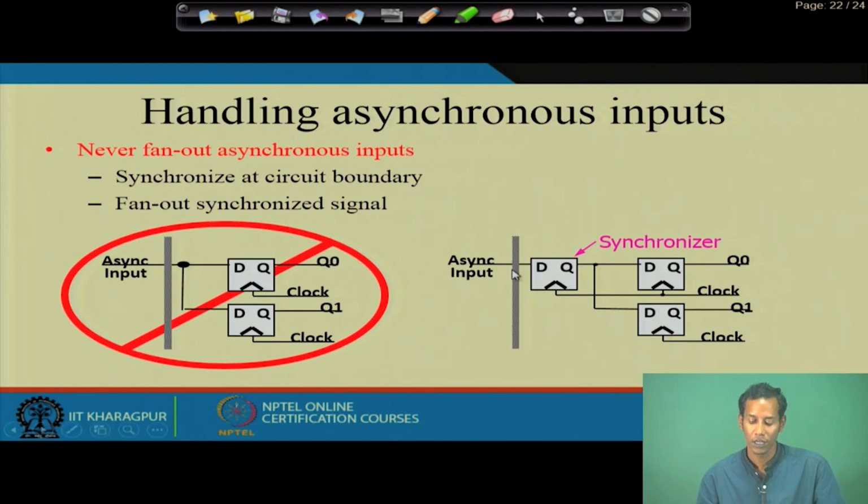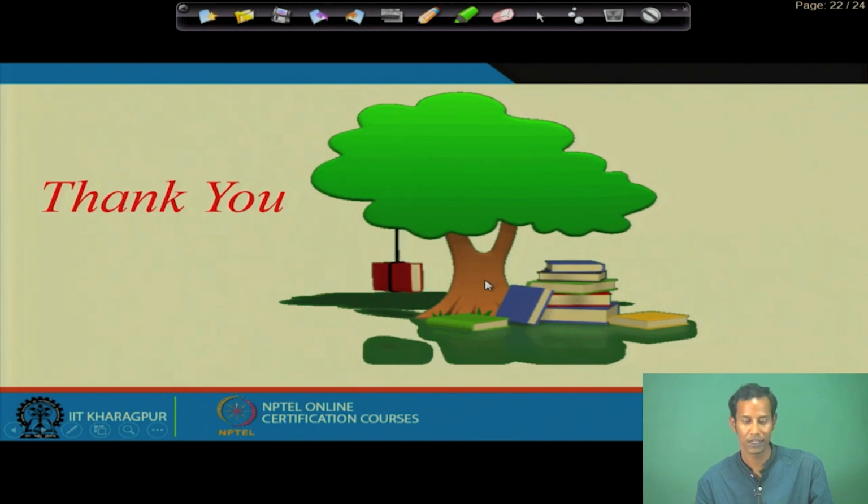Clock domain crossing means there is the sample clock, and then we have the design clock, or the integrated circuit's clock, which is the system clock. Depending on this system clock, we put this extra D flip flop on the inputs, making them synchronized with the system clock, though the inputs are asynchronous in nature.